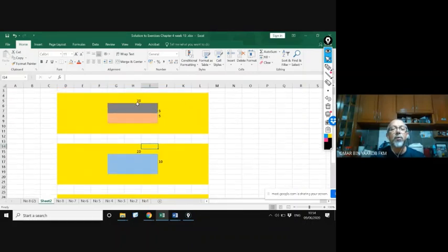So the second moment of area in the transverse direction for this one is L B cube over 12, so 1/12 times 20 times B cube, which is 5 cube. And there are 2 tanks, so times 2. Like this, you have only one tank, so it is 1/12 times 20 times 10 cube, with no multiplying by 2.